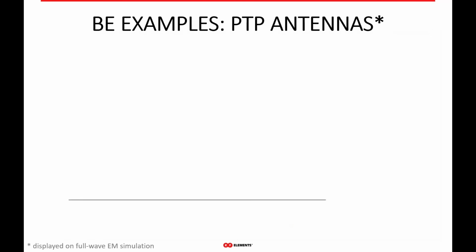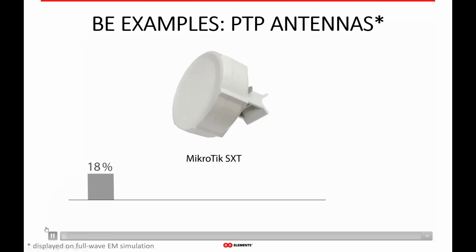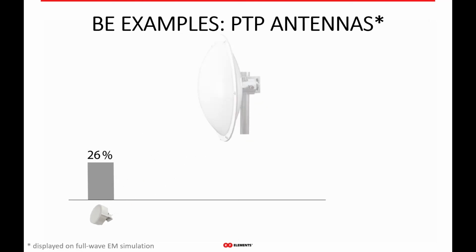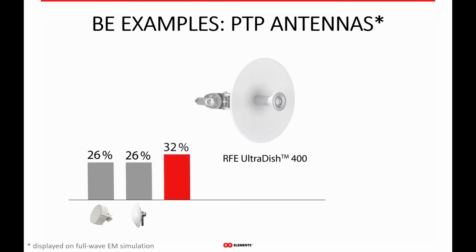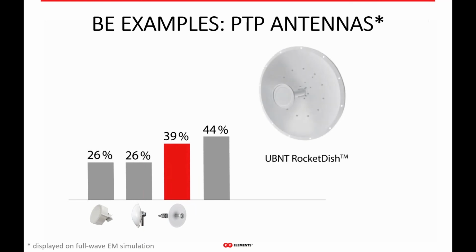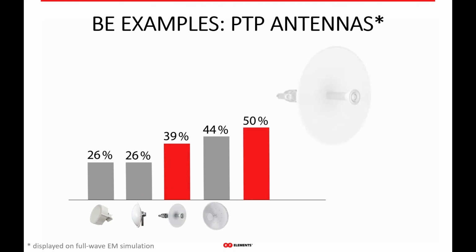So, similarly with point-to-point antennas, patch arrays are again really at the bottom of beam efficiency, due to the many frequency dependent side lobes, collecting and transmitting noise and really hurting WISP networks. Dish antennas are somewhat better, and generally, the bigger the dish, the better the beam efficiency becomes, if the antenna is carefully designed and well manufactured.